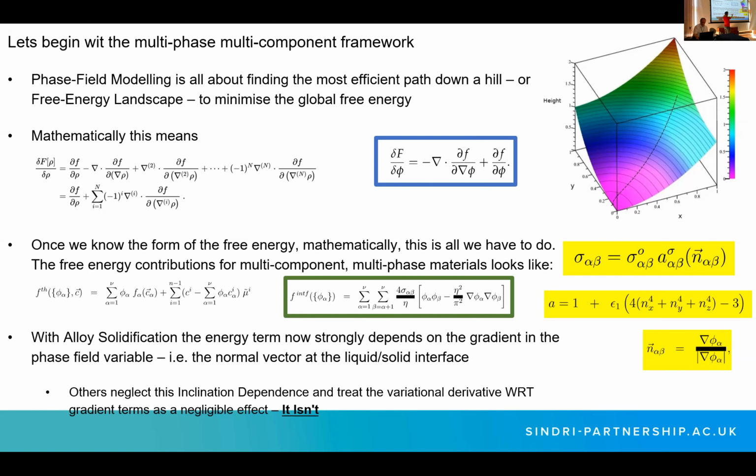But the interface component for the free energy functional, if we were to do this variational derivative where our grain boundary energy is just a constant, it's quite nice. You get these capillary terms and some bulk terms, really nice. However, in crystals, you have this anisotropic dependence on the orientation. For example, a cubic crystal, hexagonal, body-centered cubic or a face-centered cubic will have 6 planes of preferential growth, whereas a hexagonal close packed will have 6 in the basal plane and then 2 that come out normal to the basal plane. So you can have these different anisotropic functions.